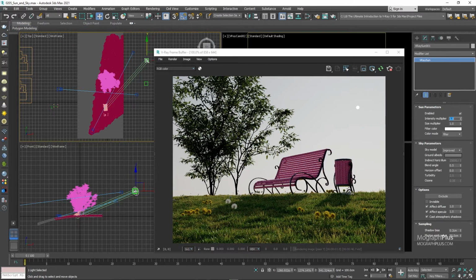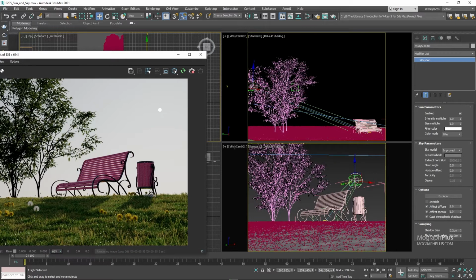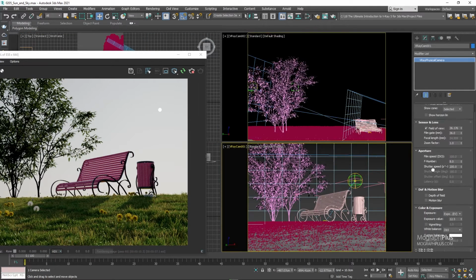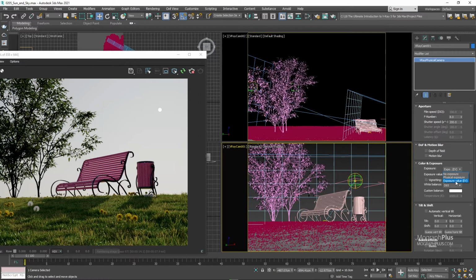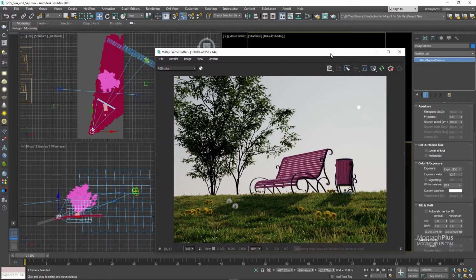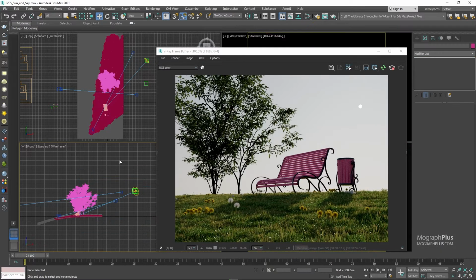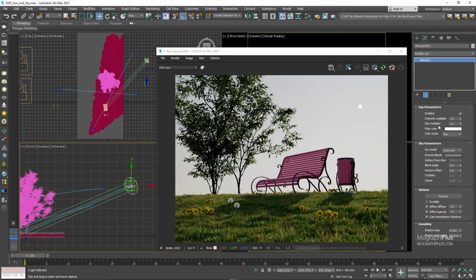1 is the physically accurate value. We are rendering the scene through a very physical camera with proper exposure adjustments. If you are rendering your scene through a perspective view, which is not recommended at all, or if you are rendering through a camera without proper exposure adjustments, you get an extremely bright blown out render when you first add a V-Ray sun and sky, which might tempt you to decrease the intensity of the sun. Do not do that. Just make sure your camera is properly exposed like in real world photography. For now, let's get back to our sun.